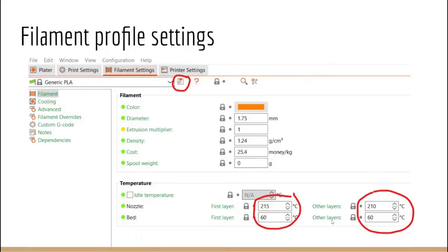Honestly, this is way more stable than the filament settings themselves for the temperature of the plastic. So you won't change these too much, but if you're having some kind of layer adhesion problem or some issue that can be attributed to the bed temperatures, then you may want to play with those settings. But again, you shouldn't have to do this.